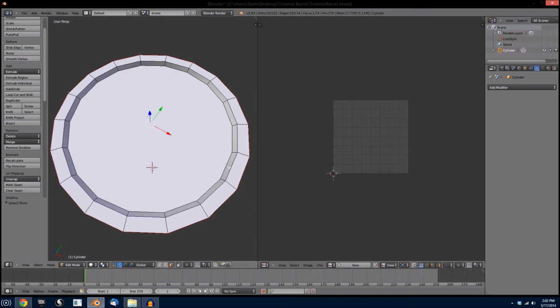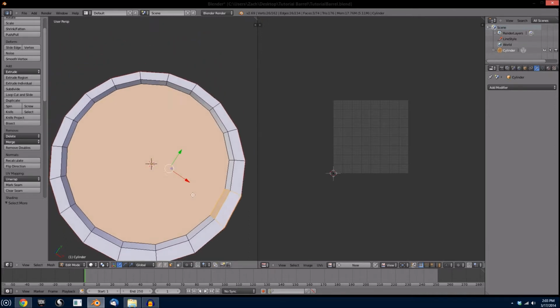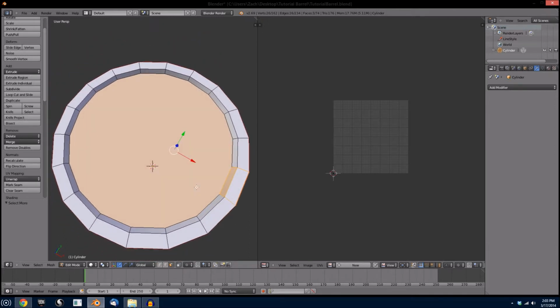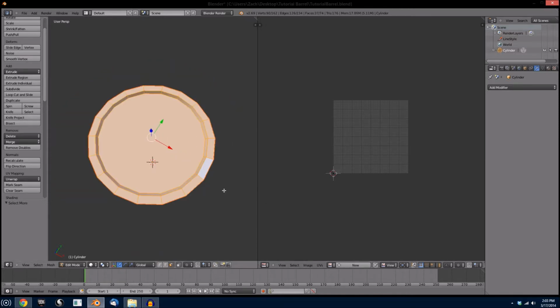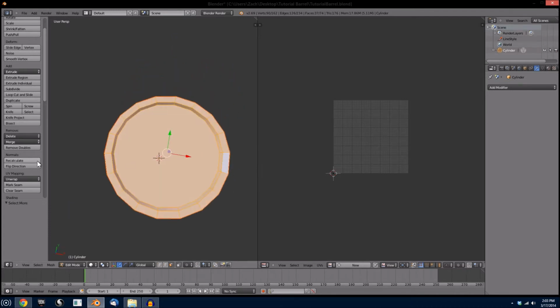We're just going to want to tap Shift and select, while holding Shift, select a portion of this top rim. And since it is edge split, it's not going to leak down onto the sides. We just, again, select more using Control plus. Selects the entire top portion. And we can use a simple unwrap.